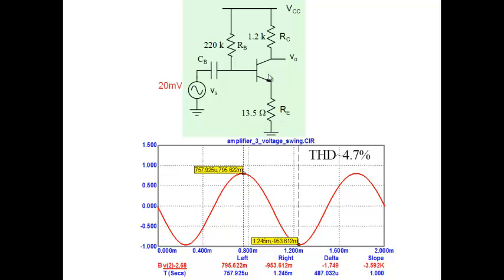And the reason that I had given earlier was about what negative feedback is doing. A signal as it goes through gets distorted. What negative feedback is doing is this: the voltage that appears here, yes, I'm saying is 10 millivolt approximately, but the 10 millivolt which appears here itself is distorted, but is distorted in an opposite manner. So when this distorted sinusoid goes through this transistor, the transistor further distorts it and sort of compensates. There's a compensatory effect, and that's why you end up with smaller distortion here.